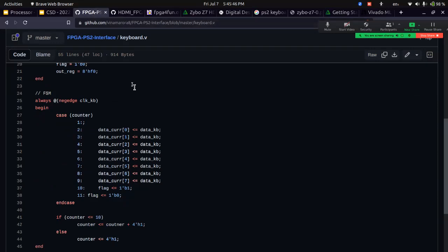It's very easy. You'll have additional modules which will monitor your module. That will make the design complex, but you don't have to worry about it. What is possible is that when you connect the JTAG programming cable to the board and your laptop, when the processor is running, this particular module which is added, the debug module, will send signals to your computer where you can monitor.